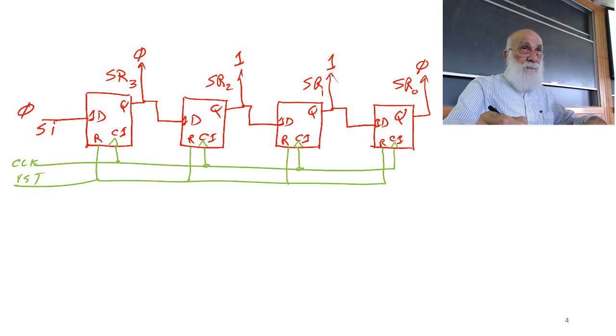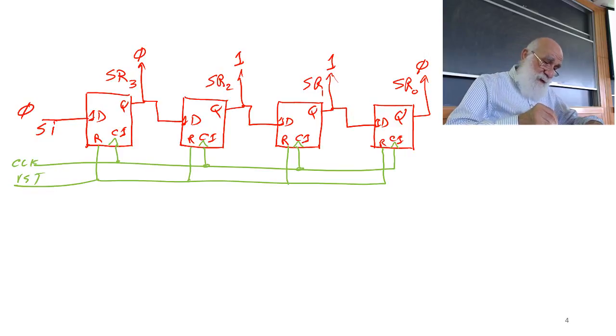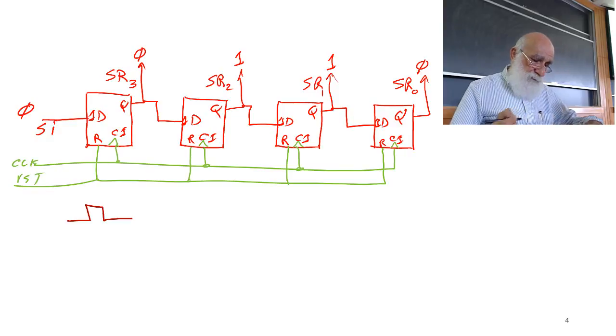This is sitting just like that without me clocking it or anything. As soon as I clock the circuit, each flip-flop, on the very first clock, is going to take its input and put it on the output.